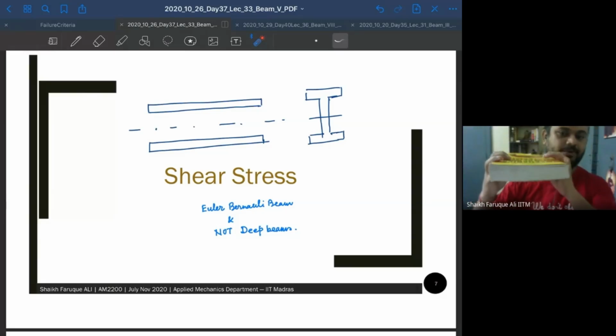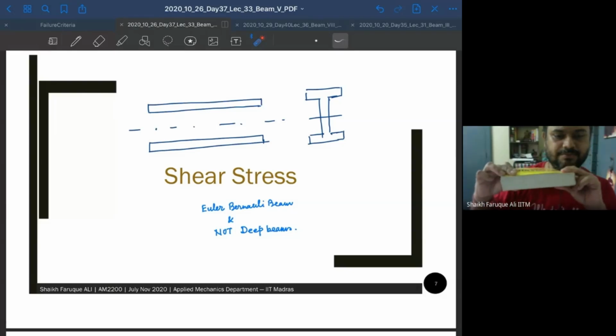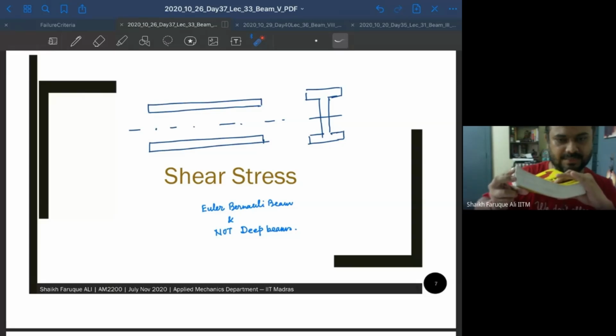So you see this book, right? And you see the pages here. All right. So assume this portion to be a beam. So this is a beam. It's supported maybe here and here. So this is a beam, and when you bend the beam, you see here at this end, the pages are going apart from each other. The more you bend, the more the pages go apart from each other. Here at this end, since they're fixed, it doesn't happen here, but it happens here.